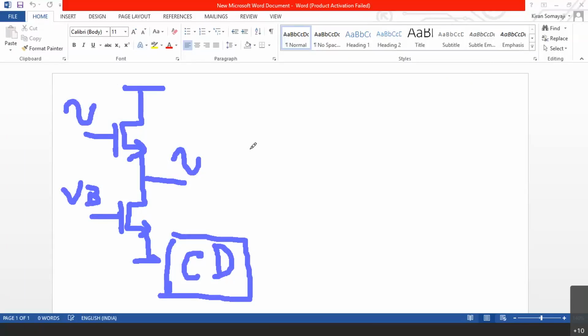So in practice, whenever we have any electronic systems, we will not have a single amplifier anywhere. We will always have multi-stage amplifiers. In the beginning, we will have a pre-amplifier, and in the middle, we will have some medium gain amplifier. At the end, we will have a power amplifier. Because in a single amplifier, all the ideal characteristics are not achievable. That's why we have different configurations.